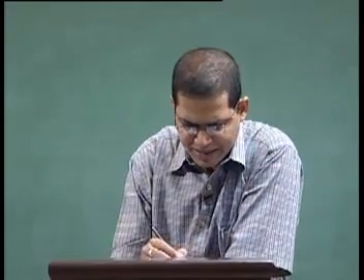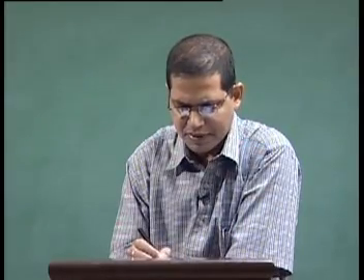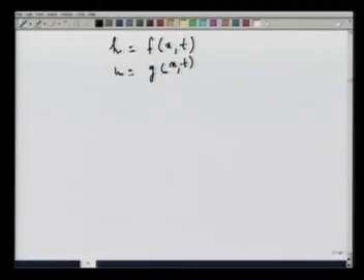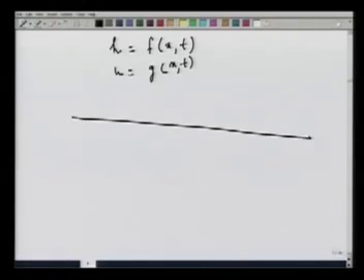So h is a function of x and t, h varies with distance as well as with time, u also varies with distance and time. So how do I define the problem? So this fluid routing problem I will define by this. Suppose this is the channel, I know at a given time the flow depth and the velocities at all the nodes. Okay. So this is called the initial condition.